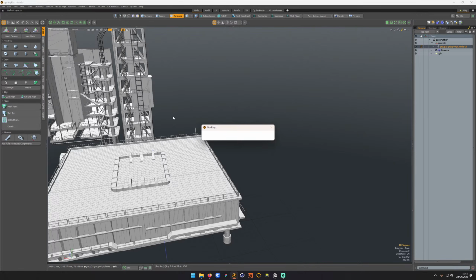I quite like using the mesh builder, the volume builder technique inside C4D. If it doesn't really need to be good geometry, then you can actually get away with quite a lot. That's basically like live booleans, but you return it into a real mesh at the end, instead of a pure, hard boolean workflow, which is not great. Maybe C4D is a place to do this.